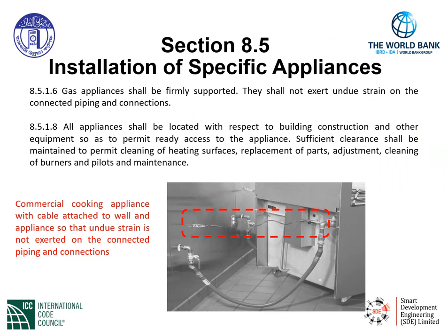The gas appliances shall be firmly supported. We're given this requirement in 8.5.1.6. We need to make sure that the appliances do not exert any undue strain on the connected piping and connections.